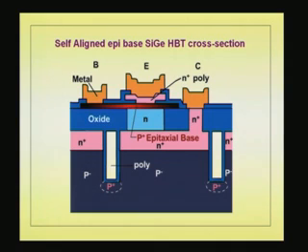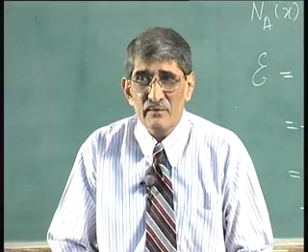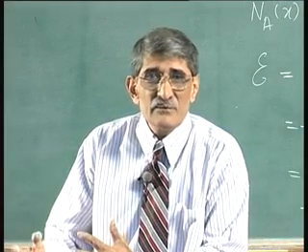Okay. That is one thing that you have to remember. But there are other issues when you want to go to harsh environments like higher temperatures. You can't use base materials which have smaller band gap. Silicon germanium has a smaller band gap compared to gallium arsenide, etc. So, for those harsh environments, you still have to take a look at the gallium arsenide based devices.